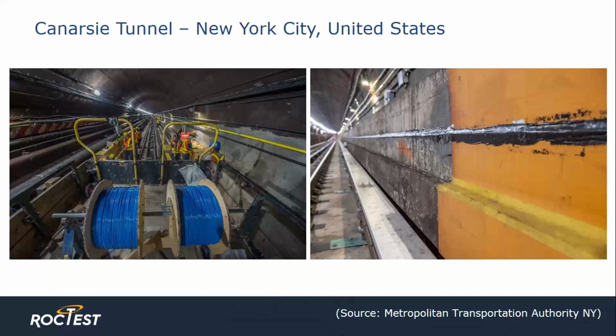The installation of Hydro&Geo cable from a work train is on the left. On the right is a detail of the Hydro&Geo cable with the protective resin over the top. The overall installation took place during select overnight weekdays and weekend tunnel closures. From start to finish, the entire project was done in a little under 12 months, with train traffic continuing during every workday. The initial estimate for the remediation was 18 to 24 months with complete closure of the tunnel.